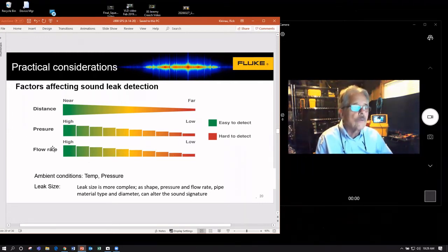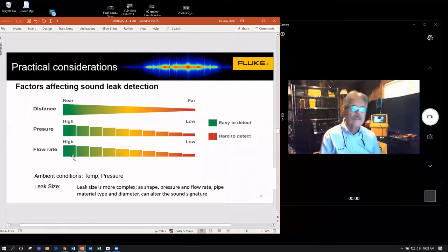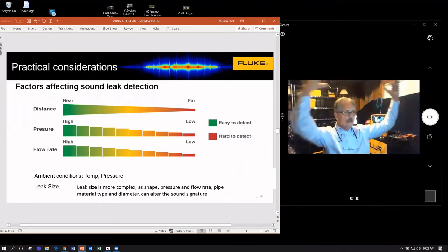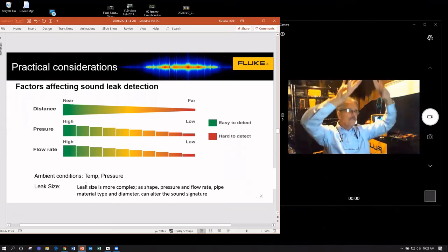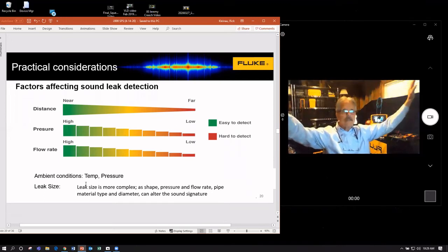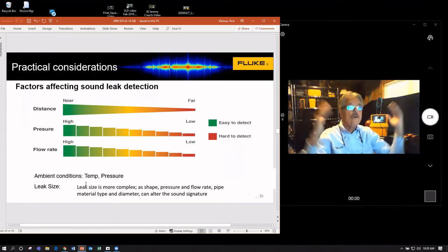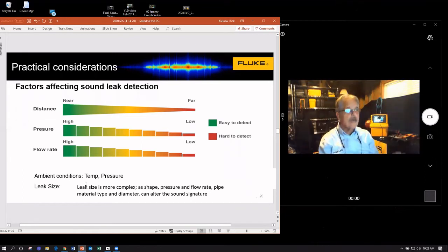And then the flow rate, that is, CFM, how fast is it escaping? Something that is a little, let me say, counterintuitive, I guess. Imagine a big fan, or a lot of times you go to an industrial site, there'll be a gigantic fan in the ceiling, okay? Flow rate's high. Those things are moving a lot of air, but they're not making any noise in the ultrasonic frequency band where we're going to be listening.